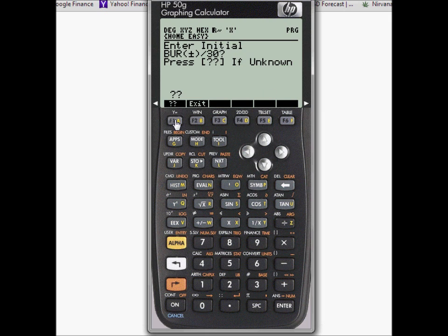Now, if it were possible, we would hit 90 degrees at the TVD of the target someplace before it or exactly at it, but this is not the case now, because if we press enter and we enter a 0 for the second curve, because there's none, it's just a build and hold, it will try to create the plan.